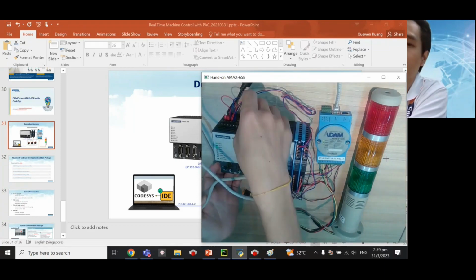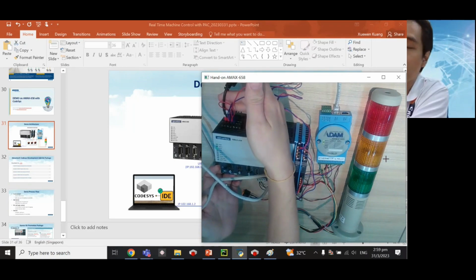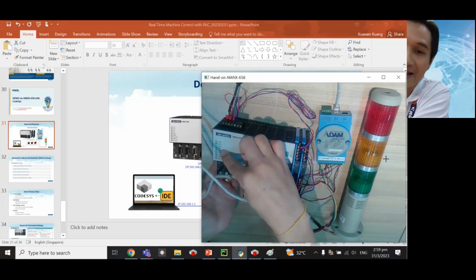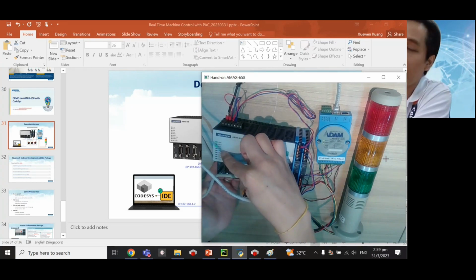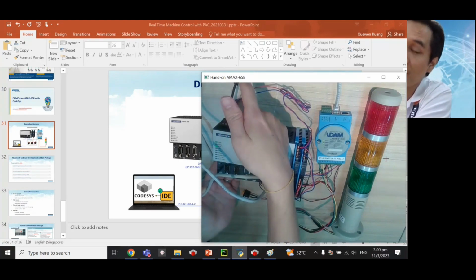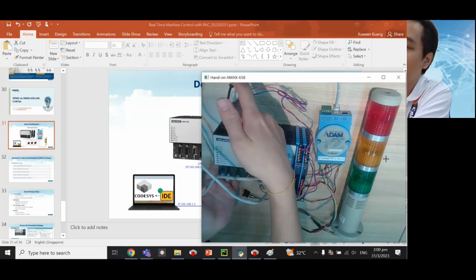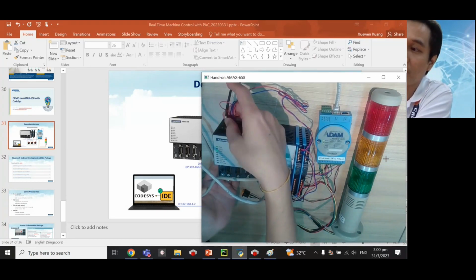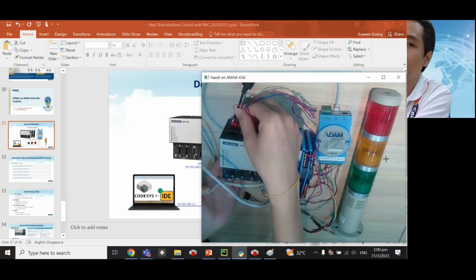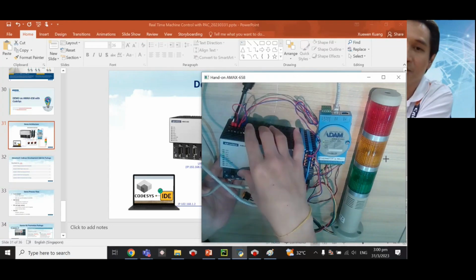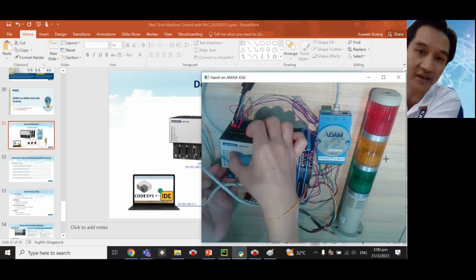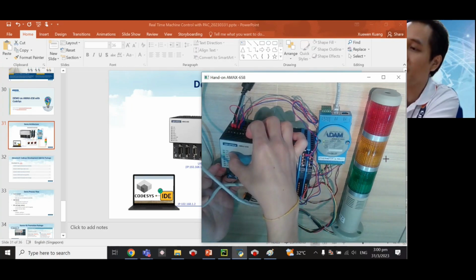This hardware supports dual power, so redundant power is available. If the ERR LED is on, it means there is an issue with one of your power supplies. The design is redundant power, so you have to supply power 1 and power 2. You will see two power inputs here. I shorted these two cables, so I'm giving the same power to both power supplies. That's the reason you don't see the ERR LED on.